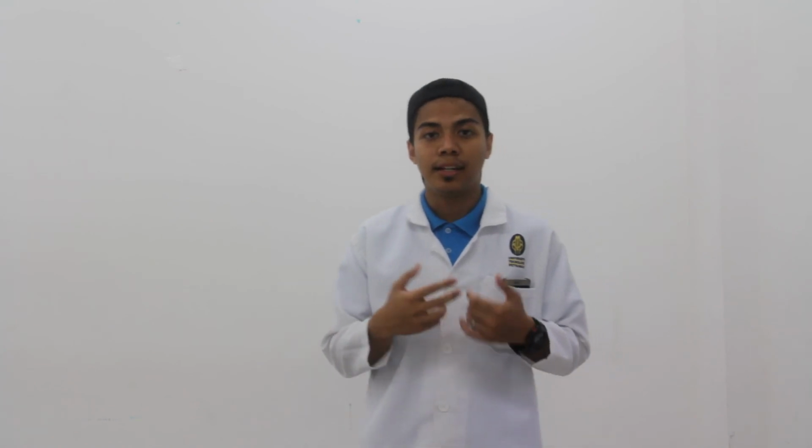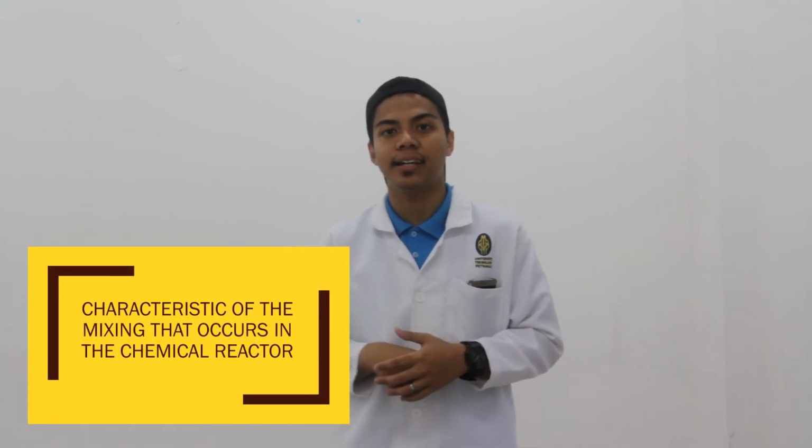So for this experiment, we are investigating the residence time distribution in a tubular packed bed reactor. What is residence time distribution? Residence time distribution, or RTD, of a chemical reactor is a probability distribution function that describes the amount of time a fluid element could spend inside the reactor. It also shows the characteristic of mixing that occurs inside the reactor.